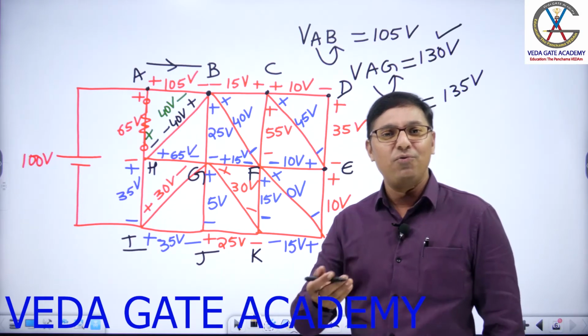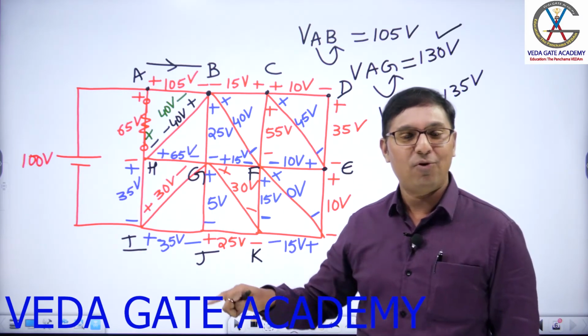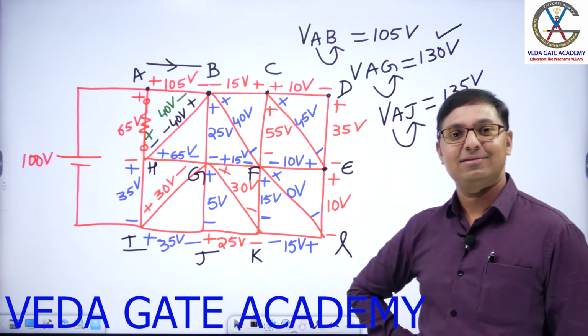What is Thevenin's voltage, sir? How do you find Thevenin's voltage? We open circuit the branch, put some A and B. Start at A, go to B following KVL sign convention. Hope you got the point.